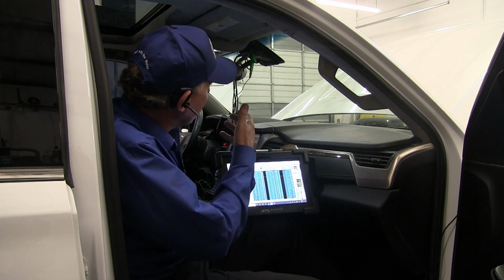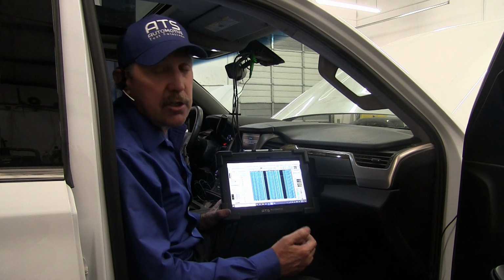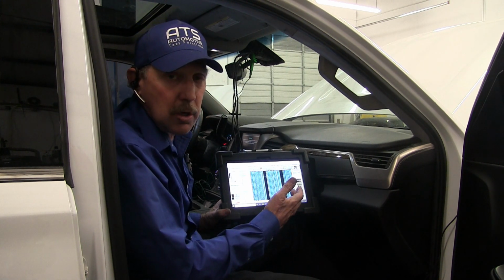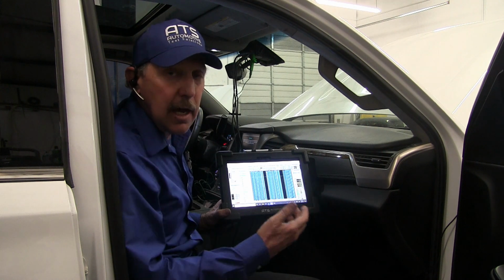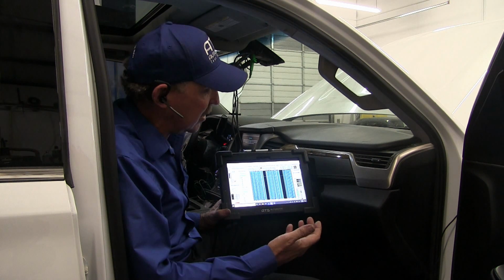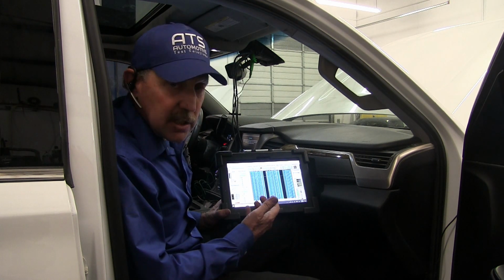And the dash is coding this camera, but it did not code it until the car was started. So in just an idle mode, even though the bus structure should be running, it never set a code. It only sets the code once the car is started, and then it runs for a few minutes, and then we're okay. So it sets the code.